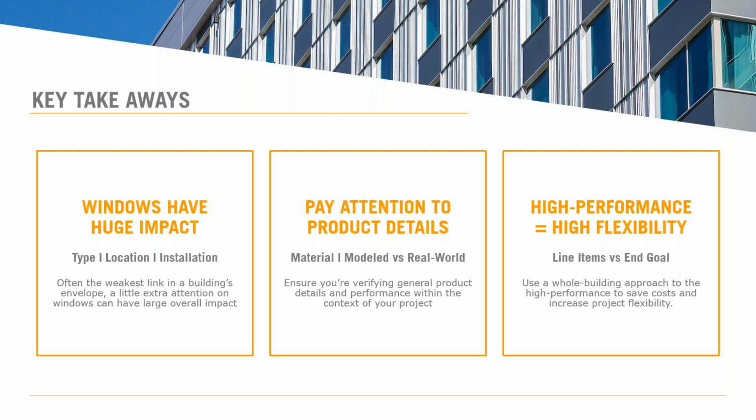Okay, so there are two options, I suppose, with our window products. You have the standard universal series, which is for punched and strip windows, and then when you go to window wall, that deflection increases because of the design of the head components. So standard is plus or minus 3/8 of an inch. I guess you get about a 3/4 of an inch overall deflection, and then if you go to the window wall components, you'll get 1.5 inches overall deflection. So hopefully that answers your question.